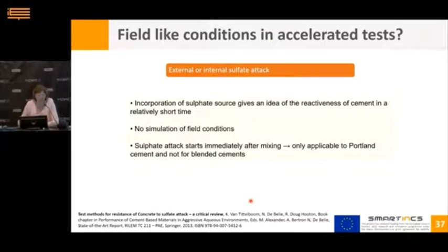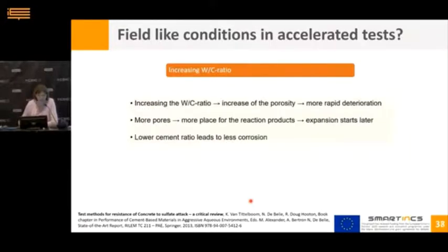In a lot of cases this does not simulate, of course, the field conditions, and it is also something that you should take care of if you have a concrete with a cement where supplementary cementitious materials are in it, because of course if you put your sulfates in it from the start, you will immediately have an attack mechanism, and in case of concrete with SCMs, curing is very important, so maybe it's not such a good idea to do this for these kinds of concretes.